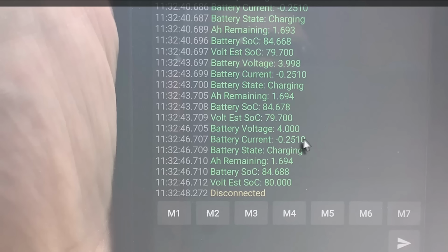Now, what you're not seeing is the solar panel is actually putting out more current than 250 milliamps because it's also putting out about 140 milliamps on top of this to power the circuit, right? So we're not seeing that current in this measurement, but the idea is the solar panel has enough to charge the battery and power the circuit. If I were to cover the solar panel, which I'm not going to do in this demo, what would happen is we'd see this charge current drop and possibly go positive if the battery has to help power the circuit along with the solar panel. All right, so that's a demo of our circuit in action using Anabit's AIoT Sense node. Let's do a deeper dive into some of the circuit elements.